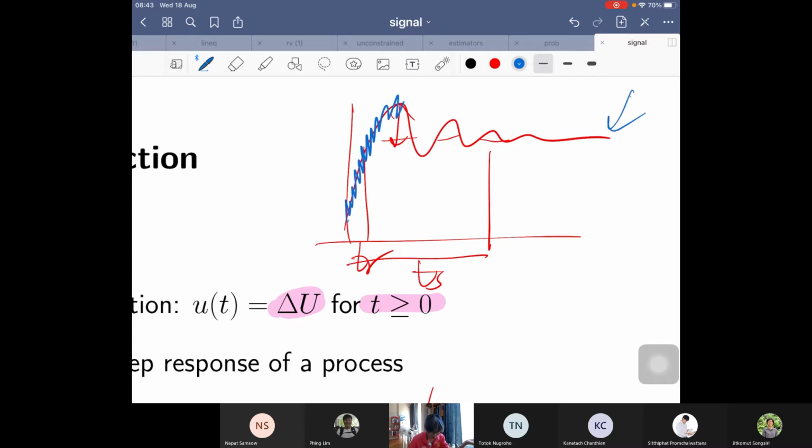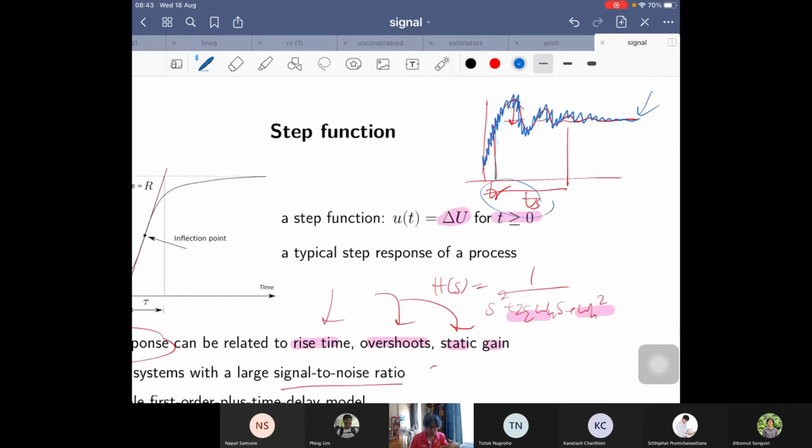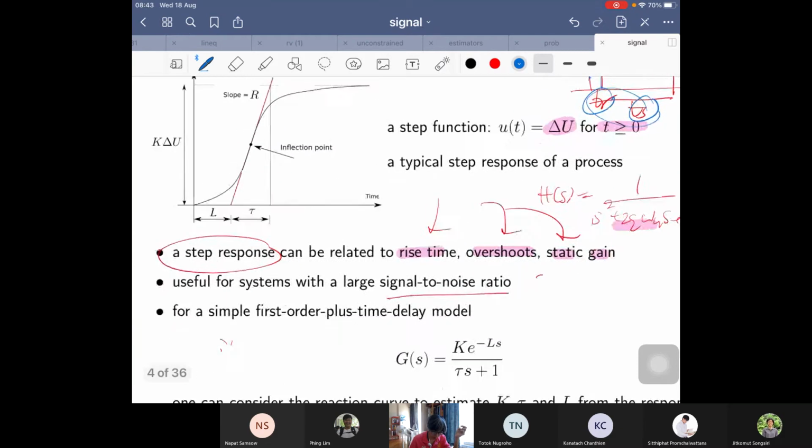What you're going to see is actually this, when it's corrupted by noise. Of course, in real life, it's going to be like when you read the graph. So quantities like rise time, overshoot, and settling time have to be assessed by the user. And when the noise comes in, it's just hard for you to get the appropriate values of those specifications.